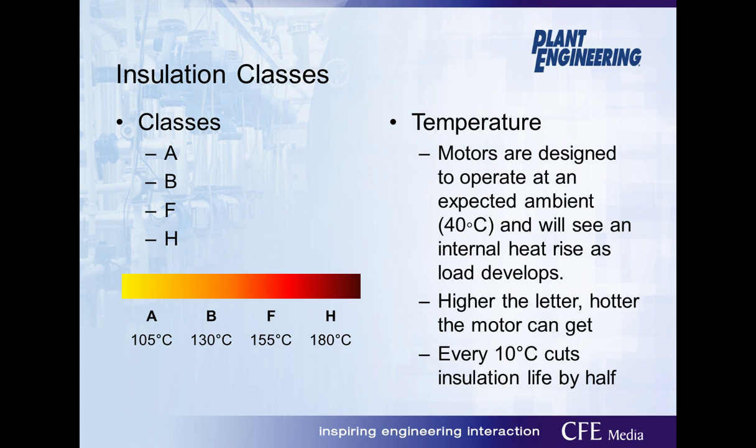Always pay attention to motor-rated ambient temperature. Most motors come standard to operate in a 40 degrees Celsius ambient, and if that is the case, it should say so on the nameplate. Also keep in mind that even though you may have a motor with, for this example, let's say Class F rating, that doesn't imply that you should expect the motor to operate at a temperature of 155 degrees Celsius.